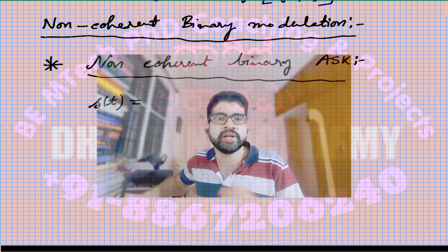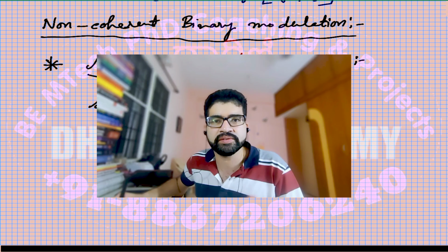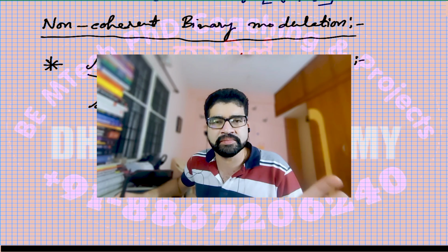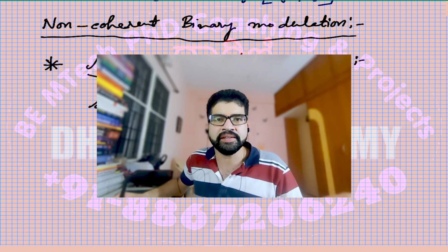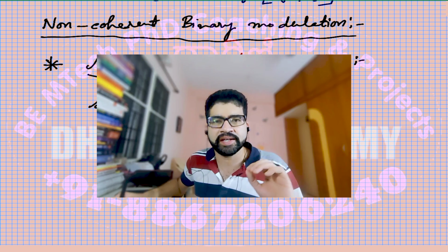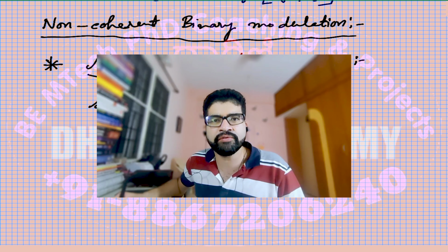So you are shifting the amplitudes. The amplitude is going to be a cosine wave whenever the symbol I want to send is 1, and you are turning off the device whenever you want to send a 0.